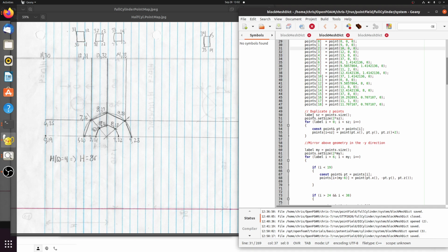So what I did was I kept Z here. It mirrors these points into Z, so it creates this geometry right here. And this is 3D. The left is back and the right is front. And so it creates this right here with this part from here to here.